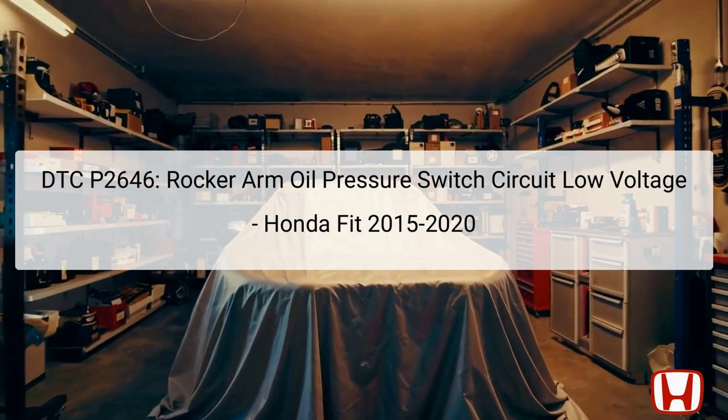The Diagnostic Trouble Code DTC P2646 indicates an issue with the rocker arm oil pressure switch circuit, specifically reporting a low voltage condition in the system. This code is significant as it pertains directly to the VTEC, variable valve timing and lift electronic control system that enhances engine performance and efficiency by adjusting valve timings. If not addressed, it could impact engine operation, leading to suboptimal performance or even engine damage.